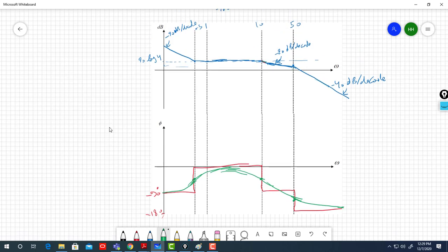But it is very important to know how to draw by hand because it helps in system identification. We told you on root locus you need to understand it, but really using MATLAB is alright. Even so, I asked you to draw an approximation by hand. Here, this is important to extract the system identification, to be able to identify a system by looking at the Bode diagram itself.